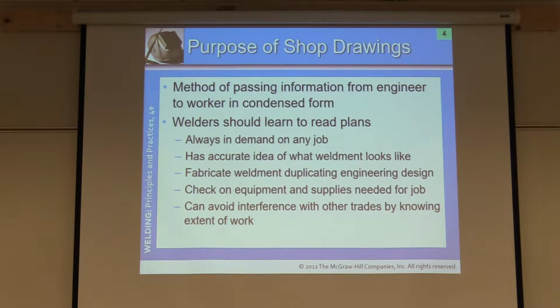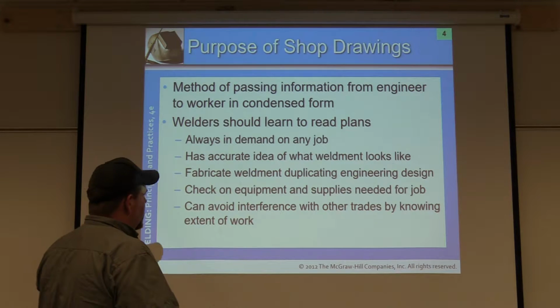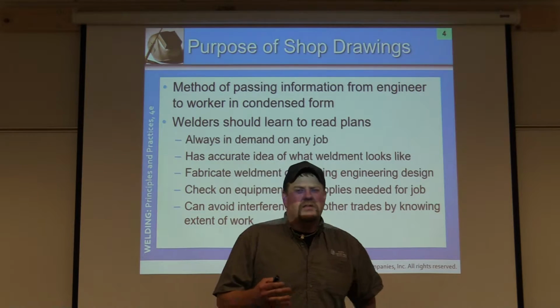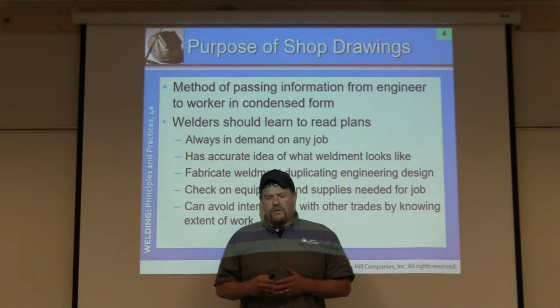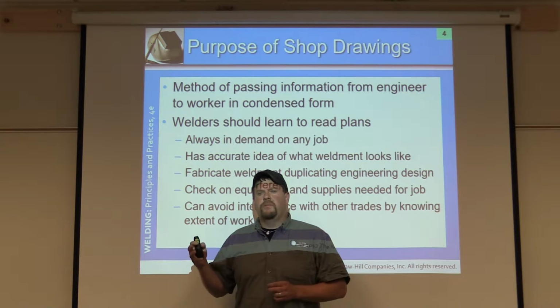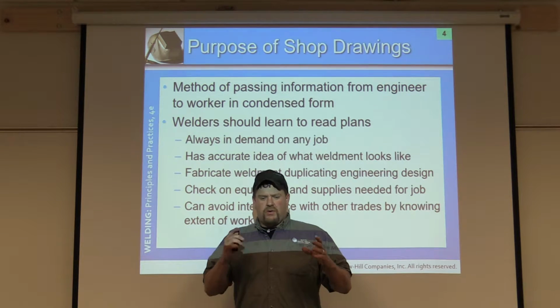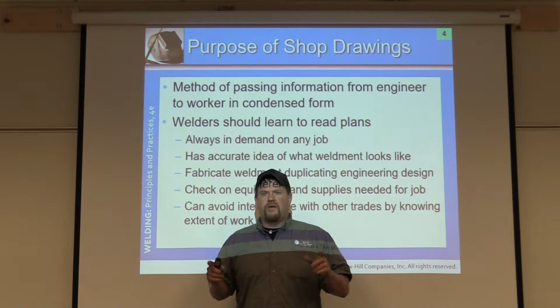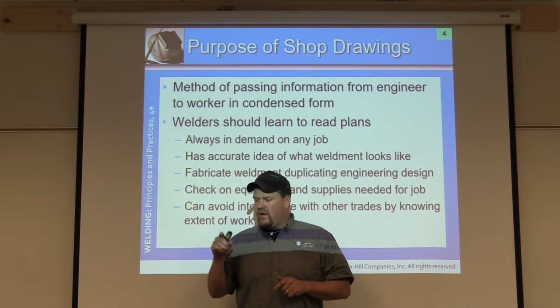Purpose, we just talked about it. You can relay a lot of information. You'll be able to plan accordingly. Make sure you have the right parts before you go into the field. A lot of times, if you're reading prints, you may do what we call a takeoff. So you might be going to the parts house to get the material before you go to the job site. So you want to look at the print, figure out, okay, 90-degree fittings, I need 1, 2, 3, 4, 5, 6.